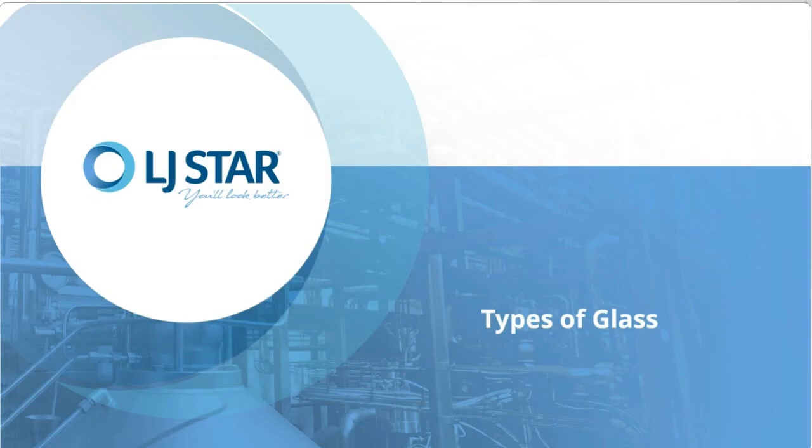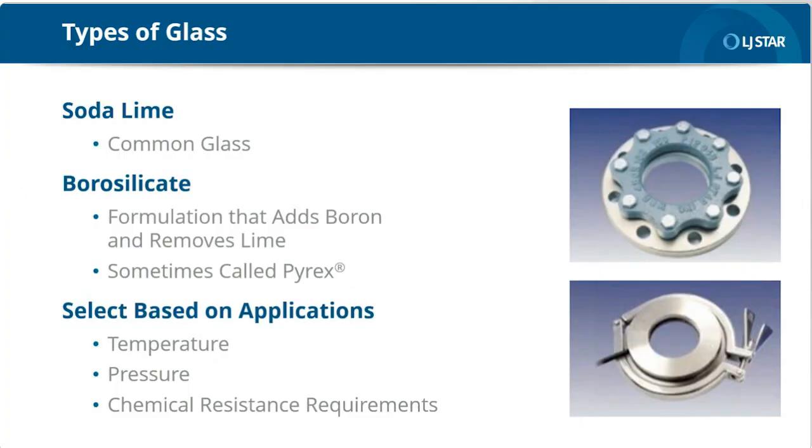Choosing the wrong glass may have serious implications, so let's compare the characteristics of the two most commonly used: soda lime glass versus borosilicate glass. Soda lime is common glass and makes up 80% of all glass manufactured. Think window glass. Borosilicate glass is a different formula that adds boron and removes lime. One trade name of borosilicate glass that you're probably familiar with is Pyrex.